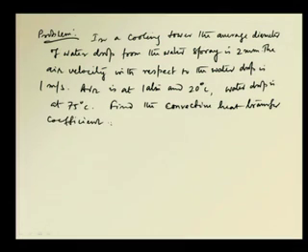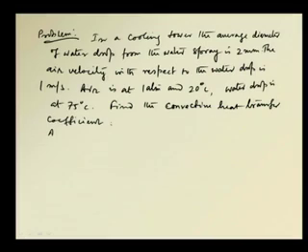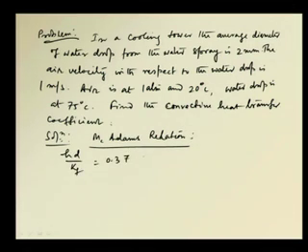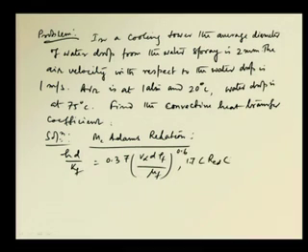So, if we try to use this, a case of sphere and fluid air, if we try to use the McAdams relations, McAdams relation says that we have seen h d by k_f equals 0.37 into (V infinity d rho_f by mu_f) to the power 0.6, for 17 less than Re_D less than 70,000.